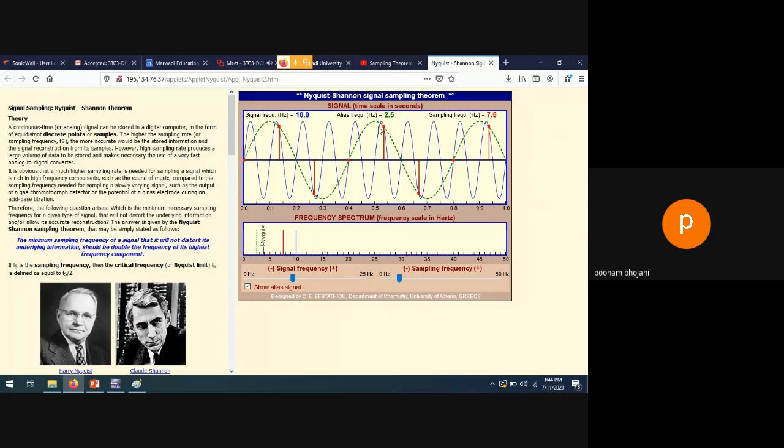But at the receiver side, if you join these red dots, can you say that you will get the same shape? No, because you can join them with straight lines also. It will give you a triangular wave. Straight line here, straight line here, so you will get almost a triangular wave. You will not get a sine wave.